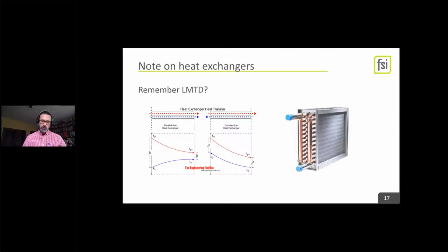So that coil has very specific characteristics. It's so big, it's got so many rows of coils, it's got so many fins per inch. Those fins are these specific dimensions, and it's very, very hard. Even if you sat there and made your intern count how many fins per inch over this coil and the exact characteristics of it, and got your calipers out and started measuring exact tube diameters, getting our reps to tell us, oh yeah, that coil has a capacity of X, is very difficult.